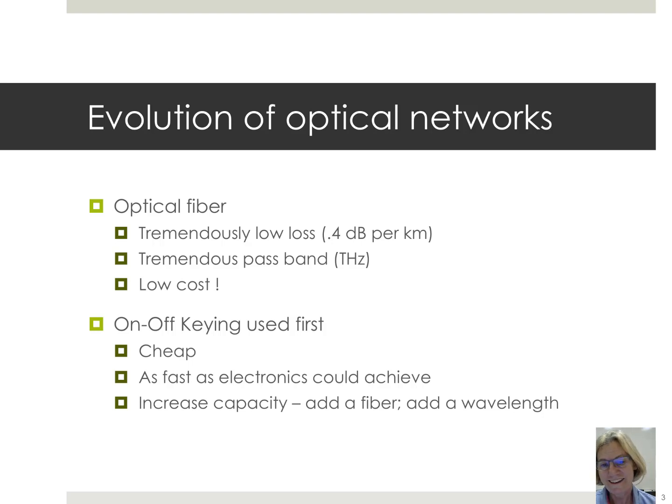Tremendous advantages. If I want to compare it to coaxial cable, the loss is in the tens of dB per 100 feet. So the loss, there's really no comparison. And the passband, typically we're talking about a few hundred megahertz for that coaxial cable if I want to keep cost cheap. And if I want to get wider bandwidth, the cost goes up tremendously.